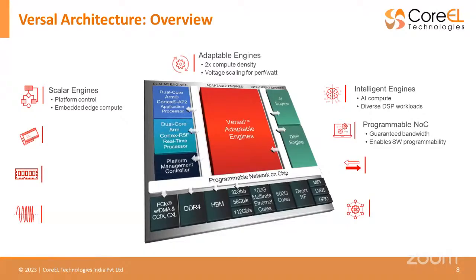This can transmit data within the chip with more throughput and more bandwidth, right? And along with that, we also have other resources like our PCIe Gen 5 resources, okay, which can help you achieve the cache coherency that is required, and the DMA bandwidths that are required for these high computation algorithms. Then we have dedicated memories. You have your DDR4 memory, that gives you the maximum efficiency when we're working with memories.